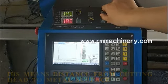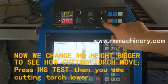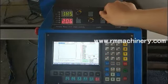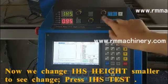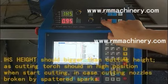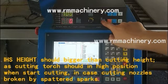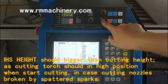Now we change IHS height bigger to see how the cutting torch moves. Press IHS test, then you see the cutting torch lower. Now we change IHS height smaller to see the change. Press IHS test. IHS height should be bigger than cutting height, as the cutting torch should be in a high position when starting cutting, in case the cutting nozzle is broken by spattered sparks.